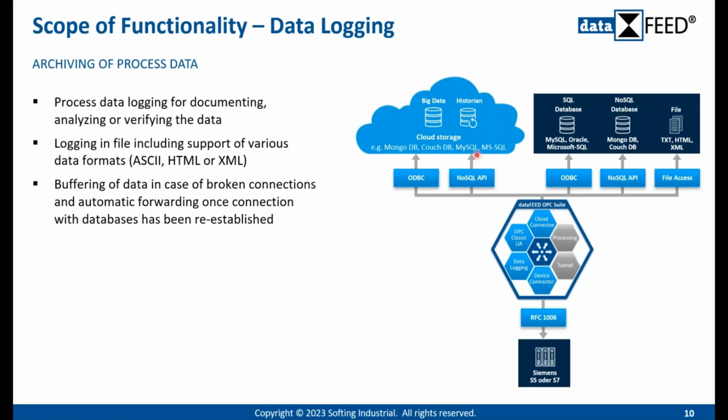In addition, what is also a benefit, we are able to store the data directly in a cloud-hosted database. It is independent of whether it's an ODBC or a NoSQL API. Why? We support on both interfaces the standard security credentials for encryption. So we can directly encrypt the communication between our suite and the cloud storage solution. So you can directly set up, for example, your SQL database in the cloud, and we are able to store the data directly into the cloud. And also here we have a store and forward functionality included, which buffers the data, and if the connection is re-established, we automatically forward this data to the database. These are the three most common use cases which are used for acquiring the data.